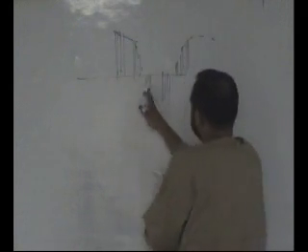You need to figure out a way to still keep the shape of the signal as is, and we know the ideal interpolator is a sinc, which is a low pass. If you put a sinc here, a sinc here, it will give you an ideal interpolation, a very nice interpolated curve. But this is redundant work you are doing, not because it is required, but because you are mixing it with the signal which is at higher frequency. So in order to translate it in frequency, you got to do this, and this requires a change in sampling rate, a lot of extra work.